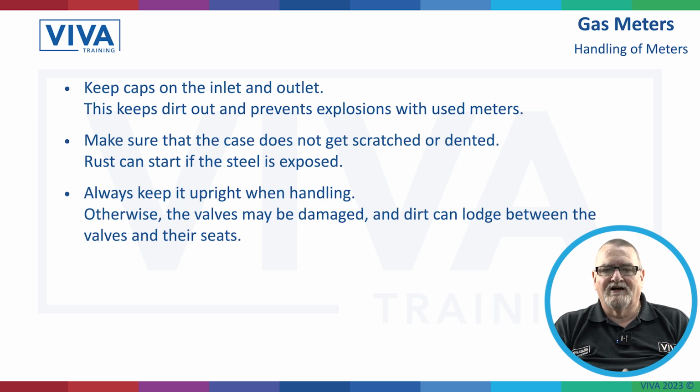We need to keep them upright, particularly the smart meters. The smart meters have got anti-tilt devices in. The suppliers are concerned that if somebody's removing a meter, why are they doing it? They might be doing it for theft purposes, stealing the meter, trying to fudge the meter, trying to bypass the meter, trying to get free gas. So therefore, that's why we've got to make sure that if we're handling a meter, we keep it upright and we treat it gently. It is a piece of equipment that measures things, so we've got to treat them gently.